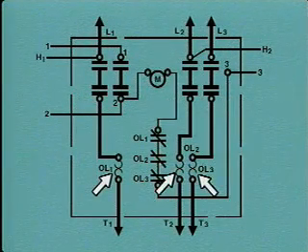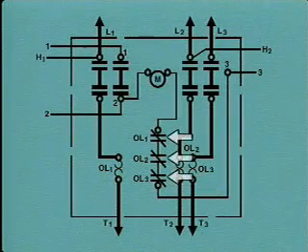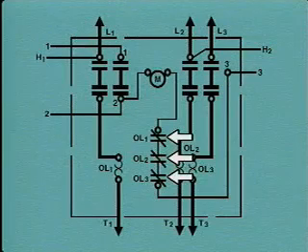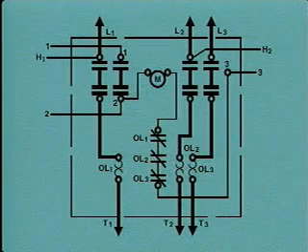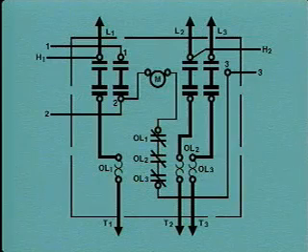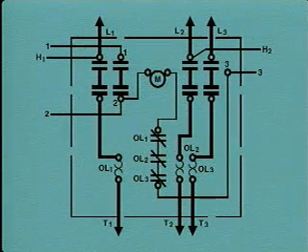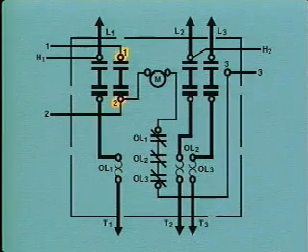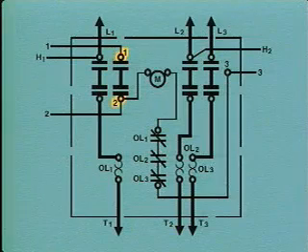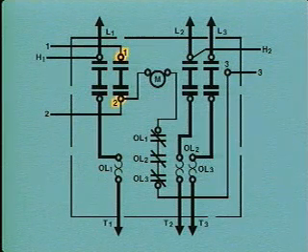The overload devices are labeled OL and are numbered 1 through 3, as are the overload contacts. The stop and start buttons for the controller are not shown on this wiring diagram because these buttons are not physically located in the cabinet that houses the controller. However, the electrical connection points for the start switch and its maintaining contacts are indicated on the diagram by the points 1 and 2.